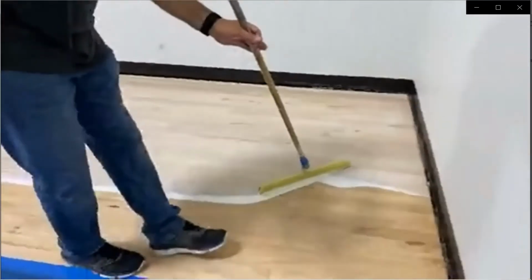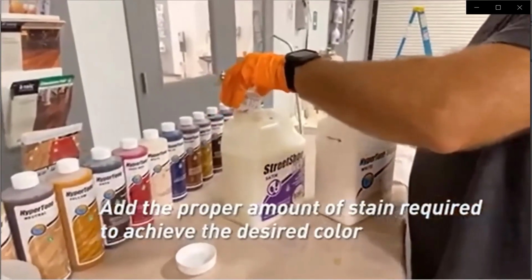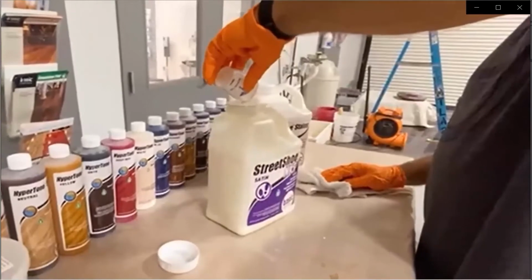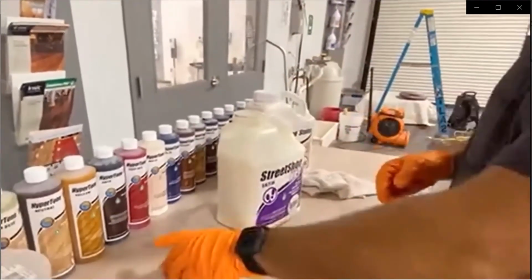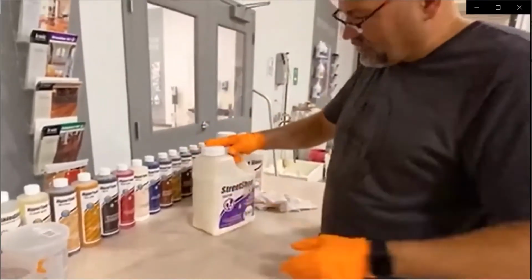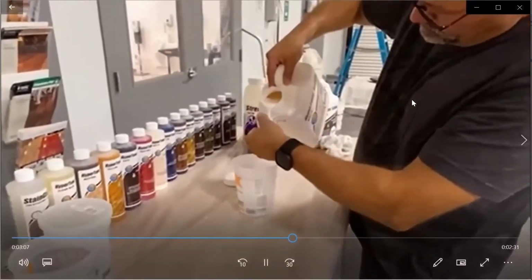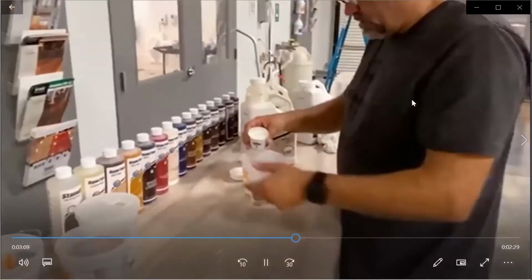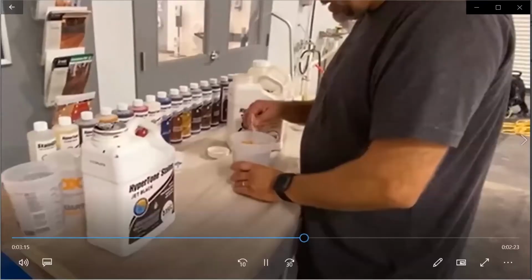The amount of stain you add to the finish will depend on the color and level of opacity you want to achieve. However, we do not recommend exceeding a 1 to 10 stain to finish ratio. This translates to a maximum of 12.8 ounces of stain to a gallon of finish. When tinting finish, mix each product separately according to label directions prior to combining. Then combine the products by pouring into a container large enough to hold the materials. Then continue to blend with a stir stick until the products are mixed and uniform in color.